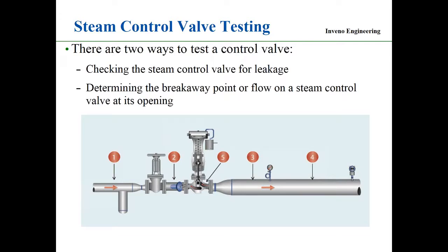Now, the same thing with this technology applied to steam control valves can be applied to hydraulic internal leakage, and other valve applications outside steam. I'm just talking about steam today, okay? So those are some of the applications that you have using it. The thing is, no internal steam valve leakage. Then we don't have to worry about premature valve failure, because steam leaking through a valve will wire draw the seat area and the valve mechanism, the plug or whatever.